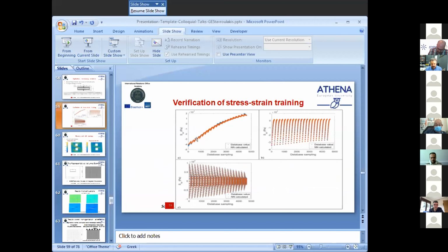Yes. You have here to correlate a tensor, that means 9 or more quantities of stresses, with another tensor of strains. You can follow several ways. The simplest way is to correlate the tensor of strains with every single quantity of the stress tensor.